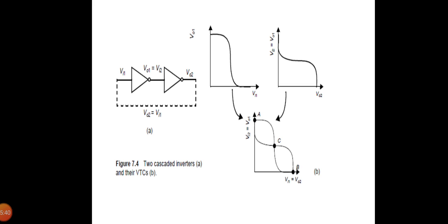For example, assume that the system is in position A, that is Vi1 is equal to 0 and Vi2 is equal to 1. Forcing Vi1 to 1 causes both inverters to be on simultaneously for a short time and the loop gain G to be larger than 1. The positive feedback regenerates the effect of the trigger pulse and the circuit moves to the other state, that is B.